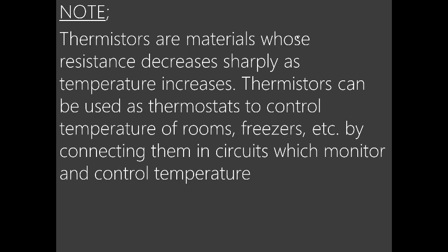Thermistors are materials whose resistance decreases sharply as temperature increases. I told you that before. Thermistors can be used as thermostats to control temperatures of rooms, freezers, etc., by connecting them in circuits which monitor and control the temperature. When temperature increases, their resistance to electrical conductivity decreases. That means they allow more current to flow at higher temperatures, so they can be used to control temperatures of rooms and freezers.